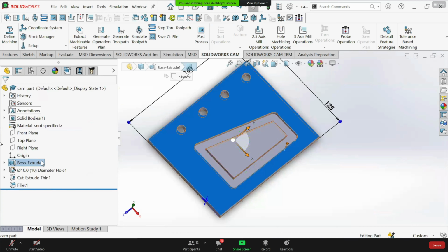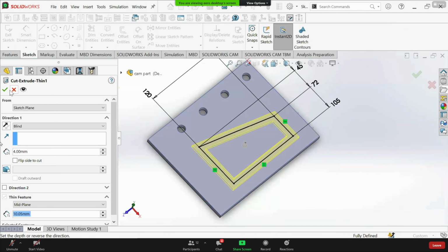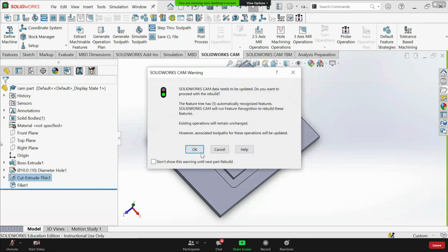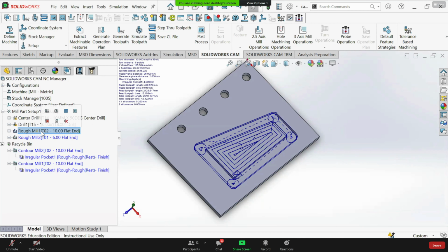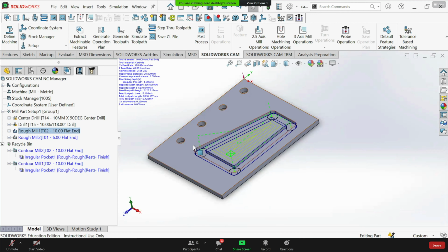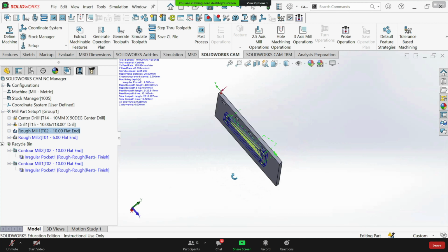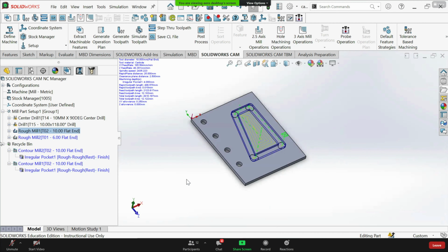What if I now change this one a little bit bigger? Let's make it now 10.05. And still it doesn't want to cut this big groove here. For some reason, the CAM software doesn't want to cut grooves directly with the end mill. It always wants to make them in one pass for one side, one pass for the other. But overall, once you get the hang of this software, it's quite useful.